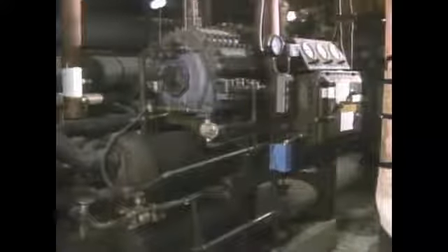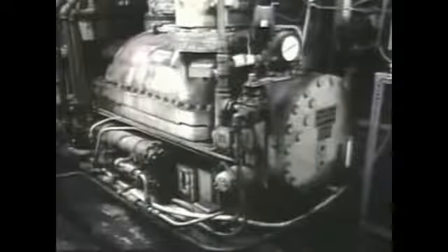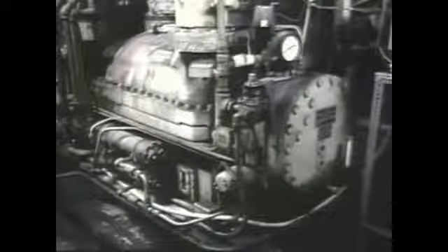Now, these controls are not the only ones you may find on a refrigeration system. For example, in some systems, a temperature instrument measures the temperature of the refrigerant and sends a signal to control the flow of water or air through the condenser. This, in turn, controls the amount of heat rejected from the system. This is another type of control system found on refrigeration systems with centrifugal compressors. This system measures refrigerant temperature and sends a signal to the controls of the compressor. This signal, in turn, controls the compressor's speed to maintain the desired amount of cooling.